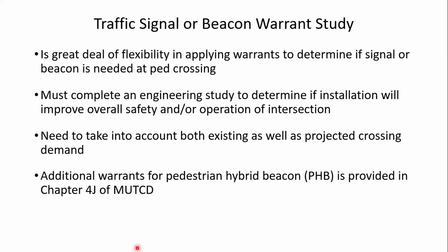And they note it must complete an engineering study to determine if installation will improve overall safety and/or operation of the intersection. And you need to take into account both the existing as well as projected crossing demand. And Chapter 4J of the MUTCD gives some additional warrants for the pedestrian hybrid beacon.